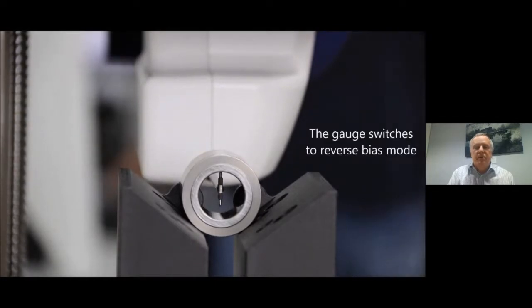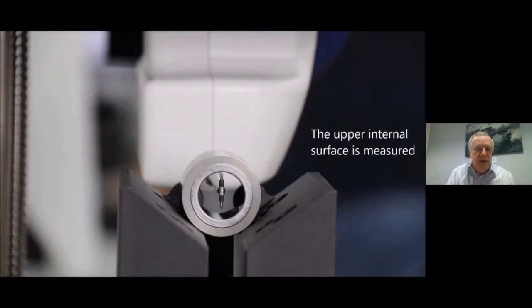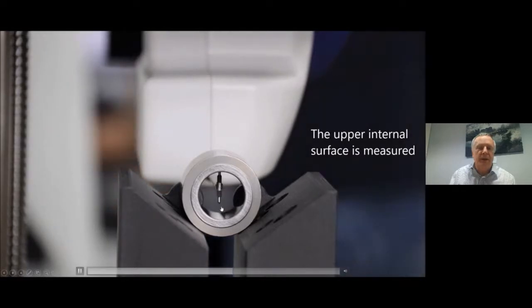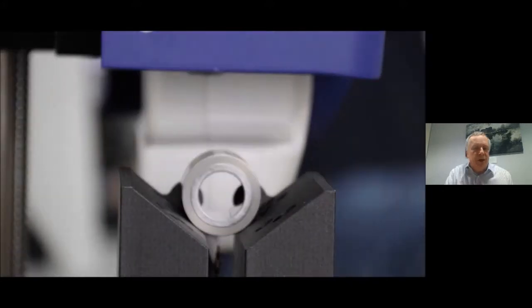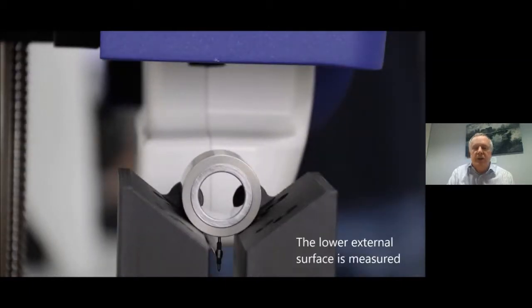Now we've switched the gauge into reverse bias. This gauge and system, the PGI Novus from Taylor Hobson, knows the precise distance between the two stylus tips here. So that allows us to measure dimensions on this bearing, and we'll see that in a minute. There's just one more trace to go underneath here, and when that's completed, we will have measured 4 traces, automatically detecting the edges. So this is the lower external surface that we are now measuring.